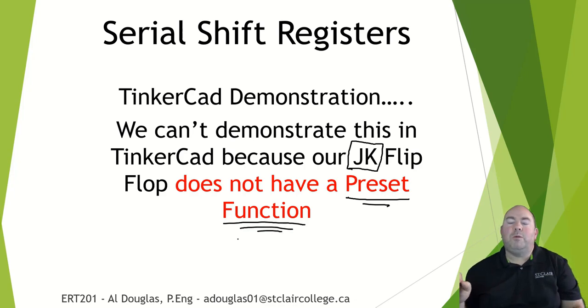So it has the clear but not the preset, and because of this, we don't have a method of getting the data into the flip-flops to start them off. We can create everything else, we can make the loop, but we don't have a way to actually get data into the flip-flops to do the parallel load of them. I tried a couple of workarounds for this, but I couldn't get anything that worked well. So we are not able to demonstrate this one in TinkerCad, unfortunately.